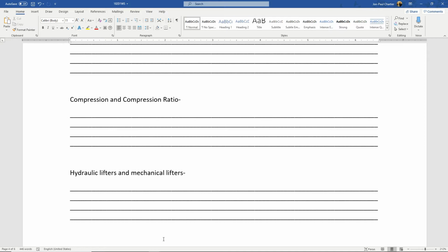That's kind of the last resort. This engine isn't running well. Does it have air? Of course. Does it have fuel? The fuel pressure gauge says it has plenty of fuel. Does it have spark? I can see the spark plugs firing. Well, why is it not running well? Well, it's got low compression. So this isn't something that will fail overnight. A spark plug will fail, right? A coil is an electrical component, it'll fail. The fuel pump is an electrical component, it will fail. Compression is something that slowly gets worse over time. So this would be an old, tired engine.